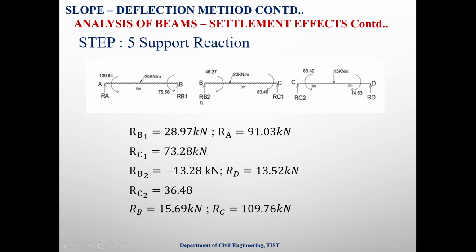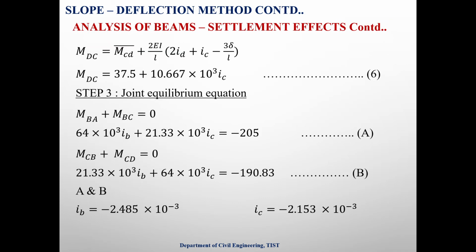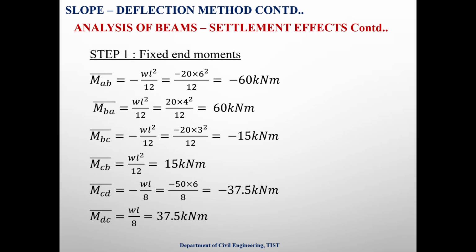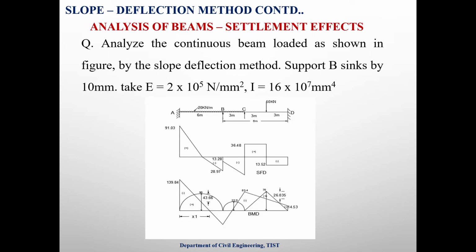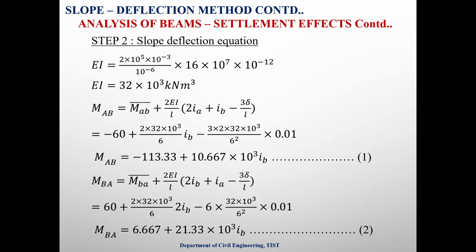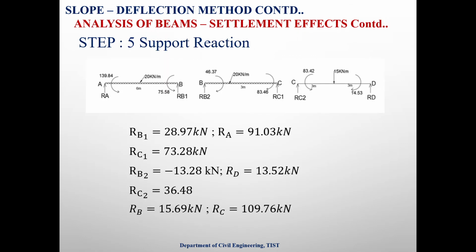etc. After getting the support reactions, by considering the support reactions and the external loads, if they are in the upward direction, mark it in the upward direction. If they are in the downward direction, mark it in the downward direction. Then complete the shear force diagram. That is the case of settlement effects.